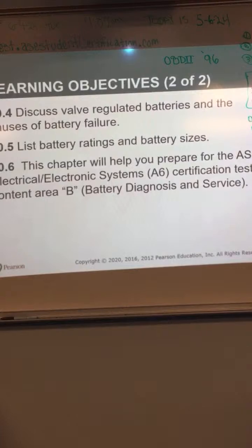How long can you leave a car without driving it before the battery goes dead? Depends on the car. Usually a normal battery will go dead within probably 5-6 weeks if you don't drive it, depending on the car, how many modules it has on it, and the weather. Yeah, weather can definitely affect that.